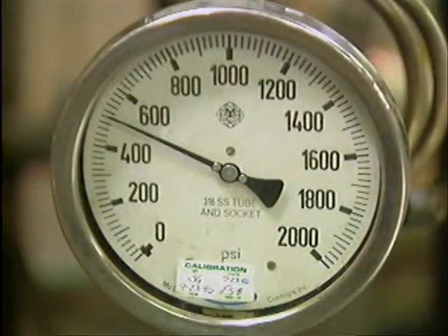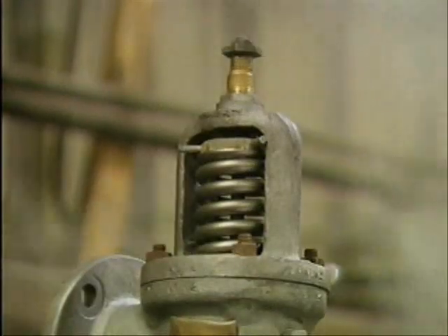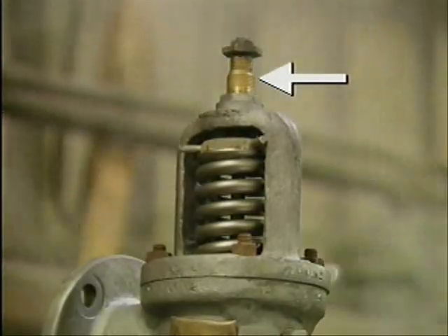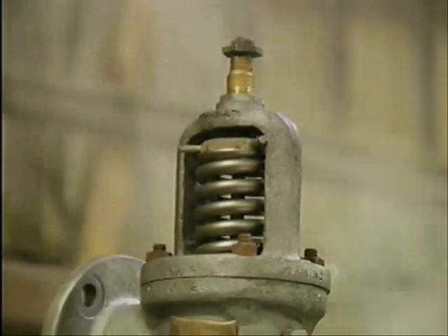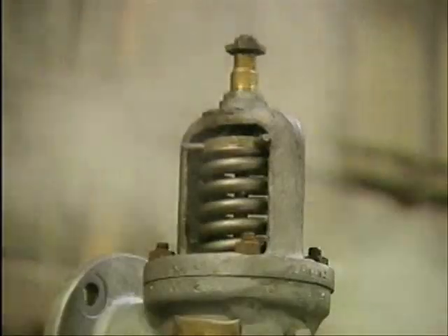In any case, when you're testing popping pressure, you're checking whether the valve opens when it's supposed to. If it opens too soon or too late in relation to the valve's set point, you must make adjustments. For this huddling chamber safety valve, you make set point adjustments by turning the compression screw. But before you can do that, you must lower the pressure so that there's no chance of the valves opening accidentally while you're working on it.